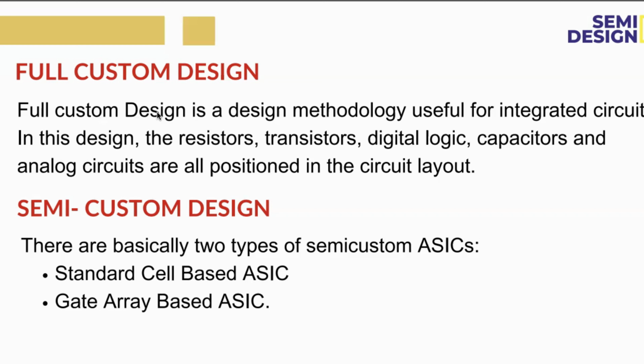If you want to develop a test plan or any test bench, we need to create the generator, the driver, the monitor, everything. There are no predefined libraries. But in UVM, all are predefined libraries. No need to develop anything from scratch. We can utilize the libraries and create according to our functionality.